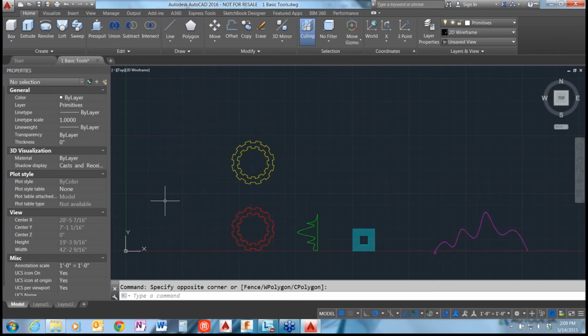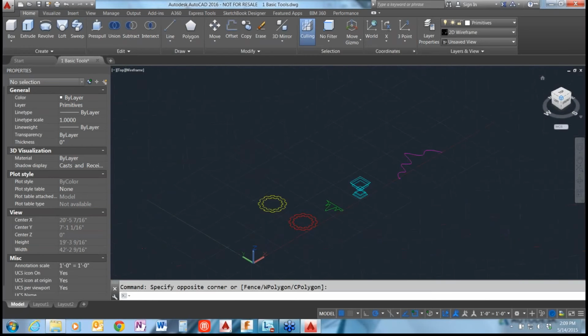So we have what's called the UCS, which is down here in your left-hand corner. You might have talked about this with Volker in the past. You have your two dimensions, your X and your Y. The X goes left to right. It's your horizontal plane. Y goes top to bottom. It is your vertical plane. And then today we're going to add in this third plane. It is the Z-axis, which is right here, and it's as if it's coming out at you from the screen.